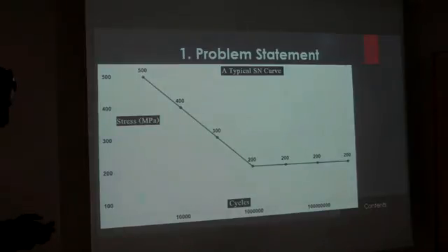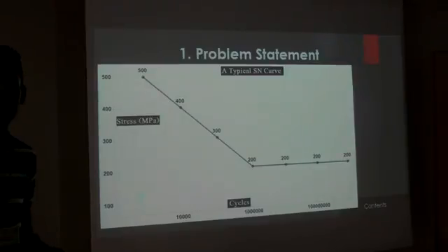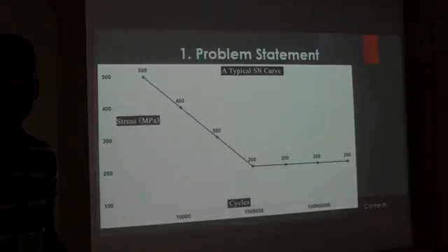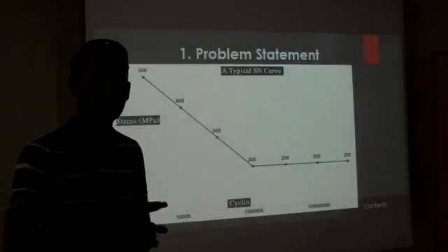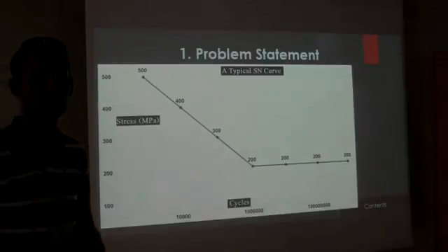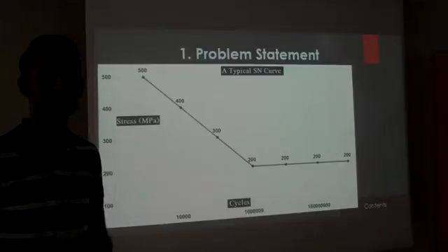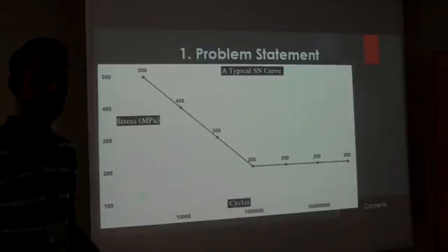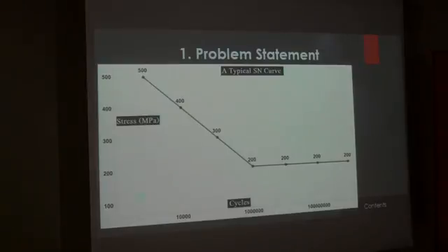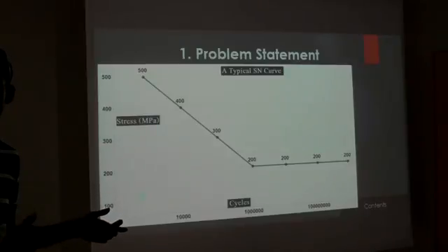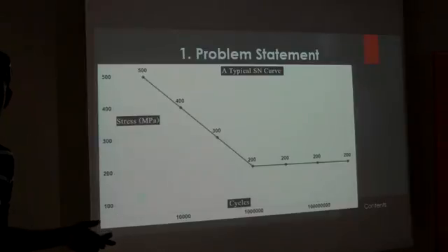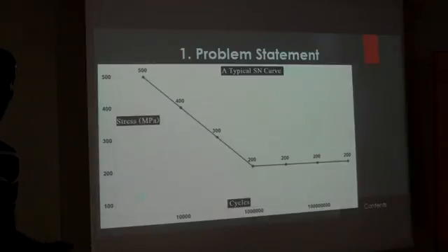Classically, we would see a typical SN curve where for a particular stress, this many number of cycles are required, after which the material failure will occur. Unfortunately, when the stress is of this kind, repeated relative surface movement, that is fretting fatigue or fretting wear, there is no such criteria or data available to accurately predict after how many cycles it will fail. So the ultimate aim is to devise something of this sort, keeping in mind all important parameters in case of fretting, fatigue or wear, and then predict that in working conditions after this many cycles the material is expected to fail.